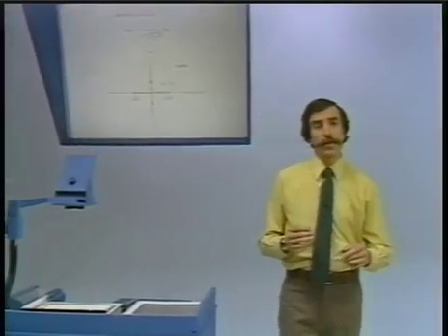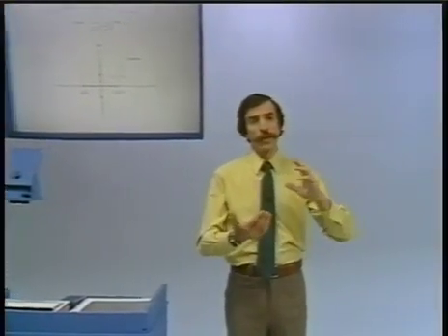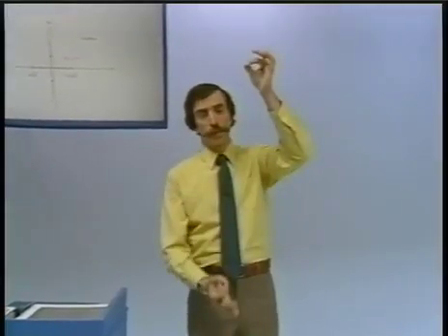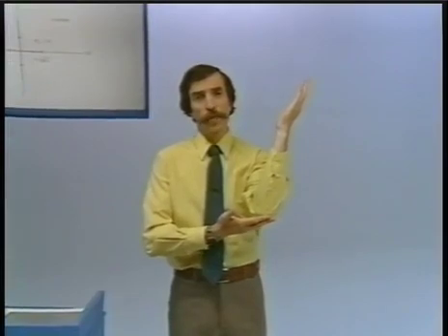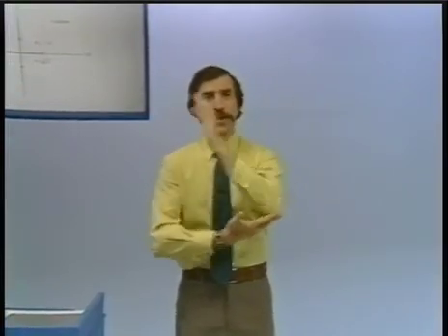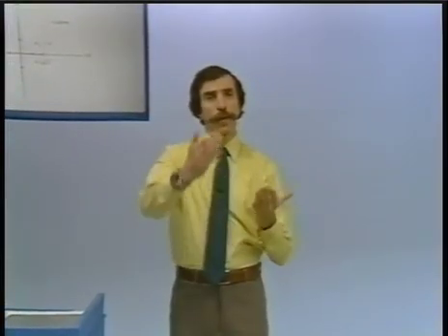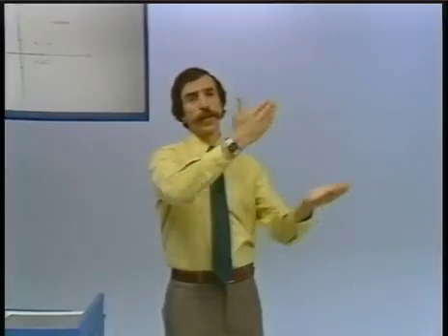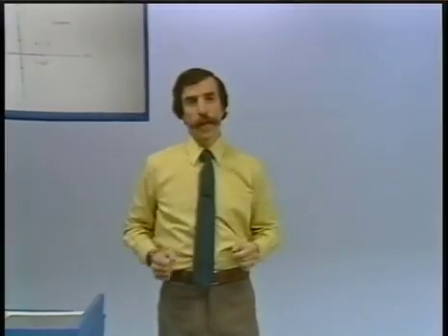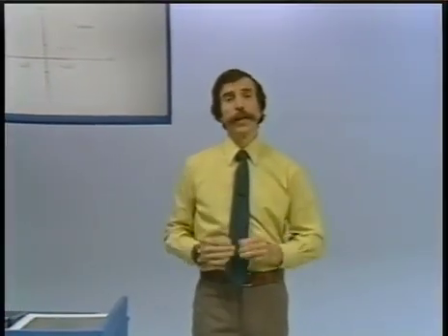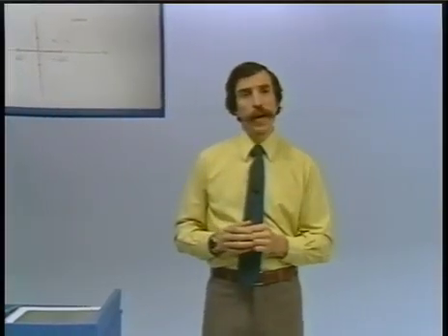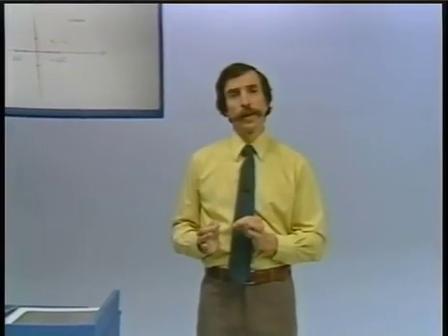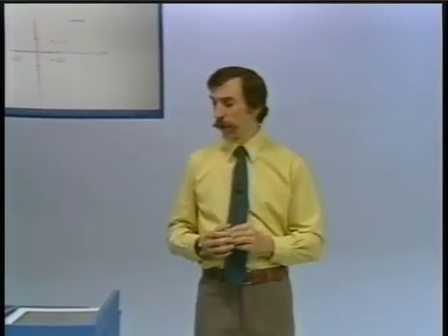And what that oscillation means is that with the measurement of the angle, essentially if the poles are operating on the j omega axis, what will happen is that things will oscillate back and forth, perhaps with the cart moving back and forth trying to compensate and the rod sort of moving in the opposite direction. In any case, what's happened is with just proportional feedback, we apparently are unable to stabilize the system.